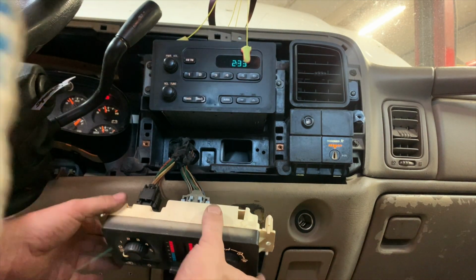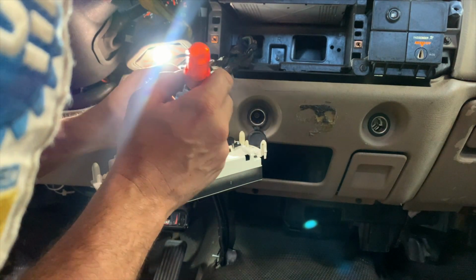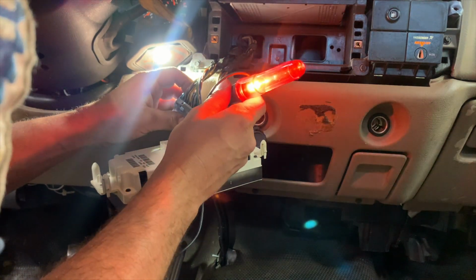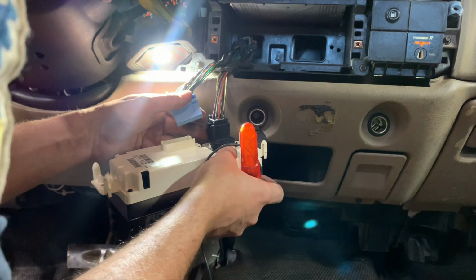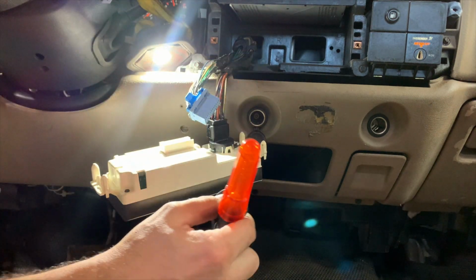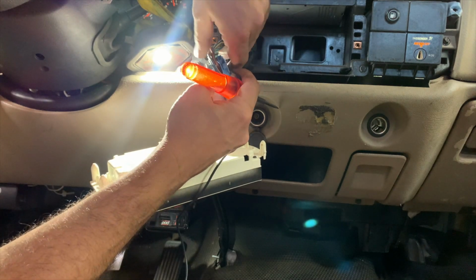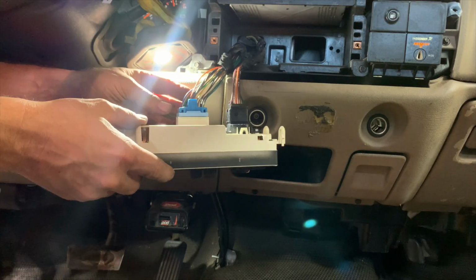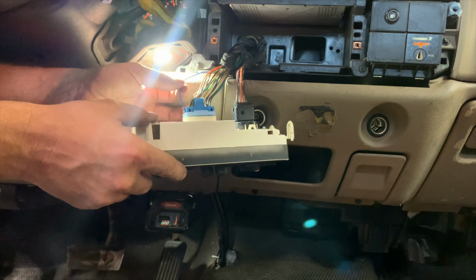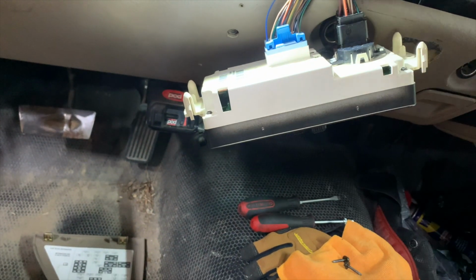All right, we'll start checking the wires. Okay, I'm checking the ground. It's pin A8. Looks like it's this one right here. And it is good. Now I'm going to check the powers. I'll switch my test light to battery negative. So when it finds a power, B5, it's a brown wire, we got power there. B12 is our AC permission. I mean, the AC pressure is good. Everything checks out here. It's got power going to the module. All the powers and grounds are good.